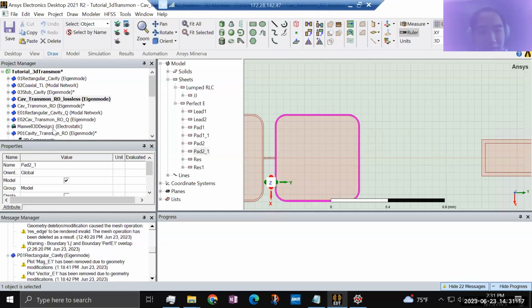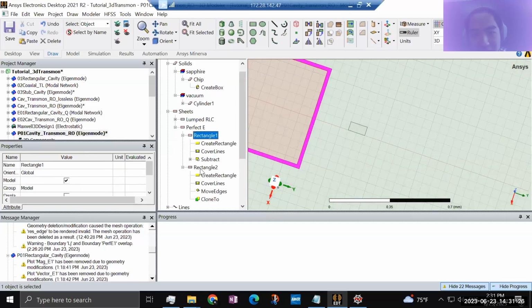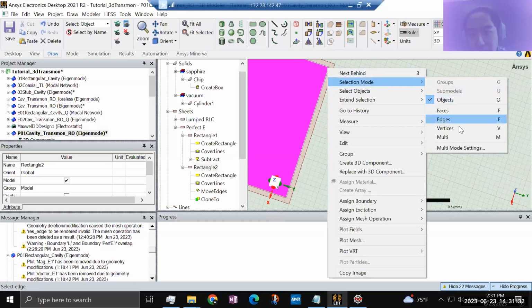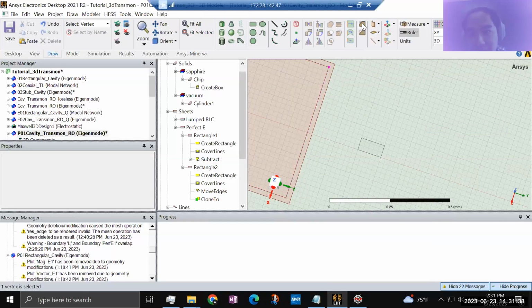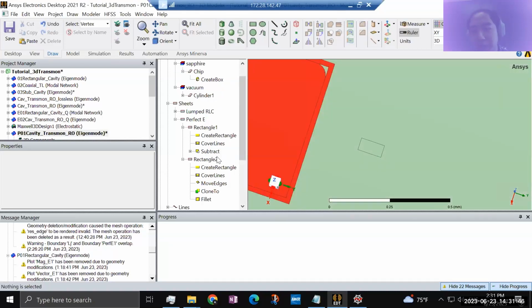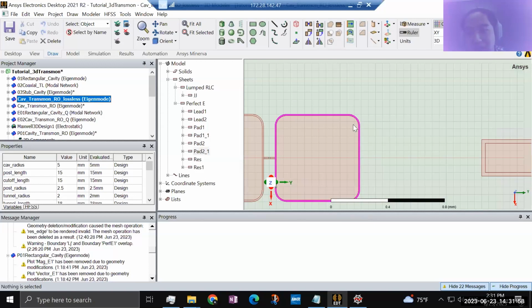And this is very easy to do in the design by just selecting this element and picking a vertex, which is this, and doing the fillet from here. We can define the fillet to be, say, 50 micron, and then it'll do this. If you do this before we do the clone and duplicate and do this edging, then the edge elements will also have the same fillet that looks like this.